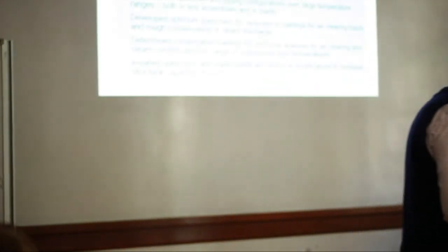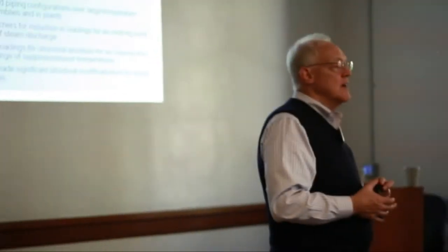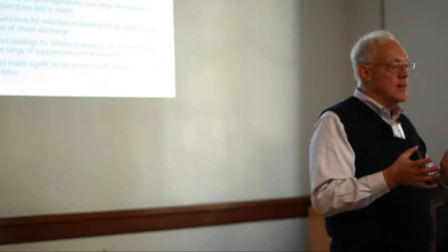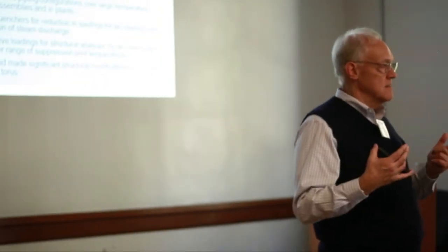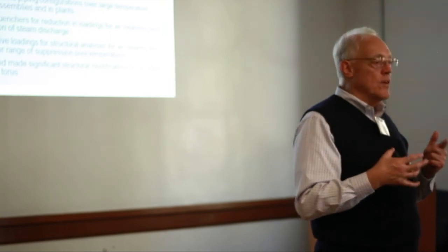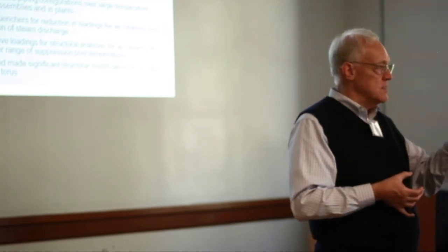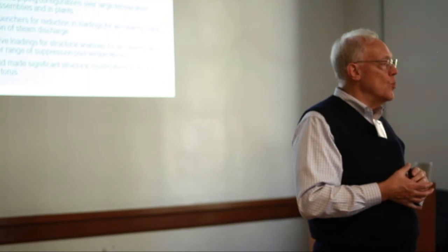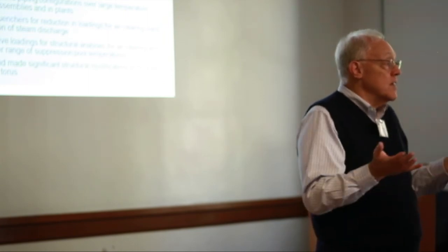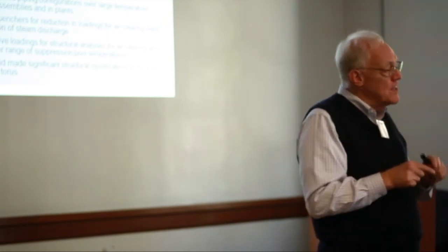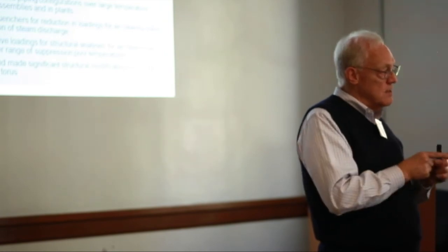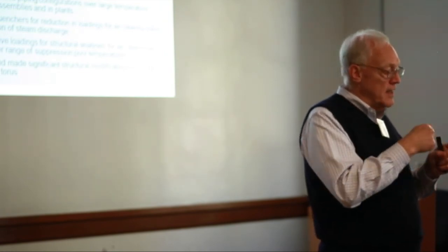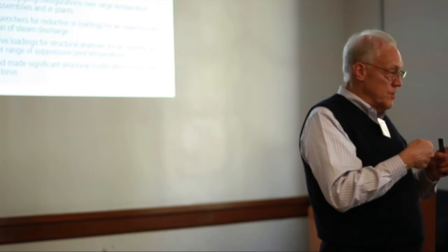The result of the TMI-2 accident was kind of the driver to it, but it was already in motion. And that said, let's go to a symptom-based thought process, where we're not going to try to predict what the event is that's going on. What we're going to do is use plant parameters that suggest to you what might be going on, not to tell you what the event is, but what your response should be to the indications that are available to you as an operator.